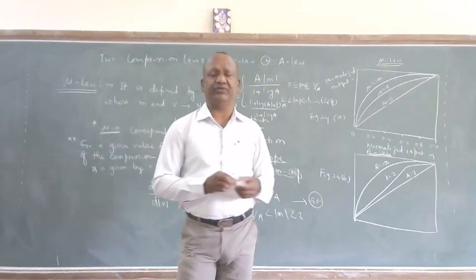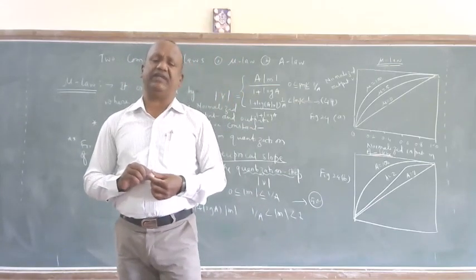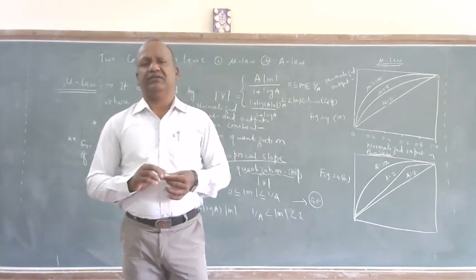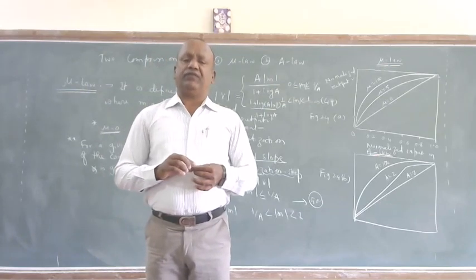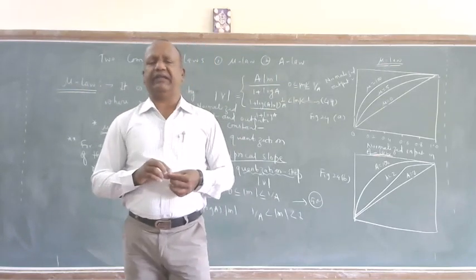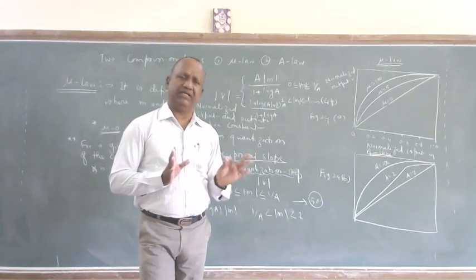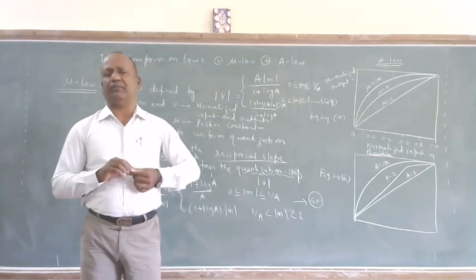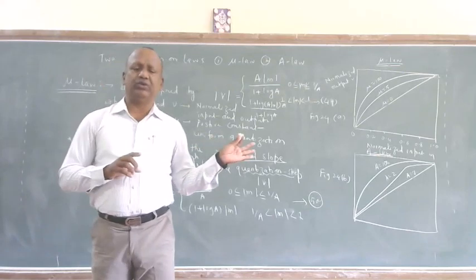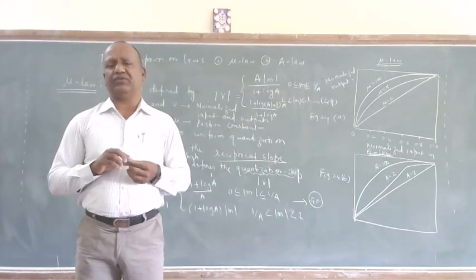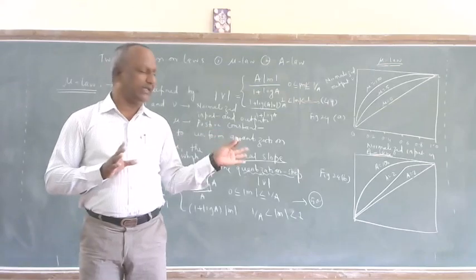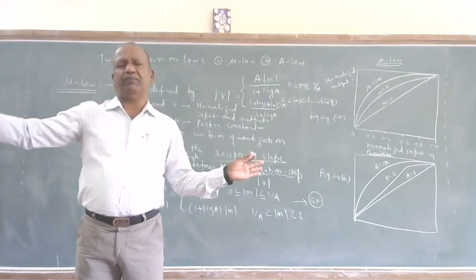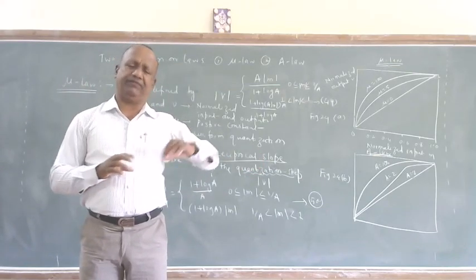So there are only two standards we use for PCM systems as part of telecommunication, because initially the PSTN, public switched telephone network, was implemented with the objective of transmission of voice only. Now over that, TV and everything is implemented. Now it is multimedia, but initially it was designed for transmission of voice. When we want to transmit voice over the public telecommunication network, ultimately we need to do A to D conversion. At the time of A to D conversion, we use quantization, particularly a non-uniform quantizer, because your voice varies between loud talk and weak talk with a different range of voltages, and we prefer a non-uniform quantizer.